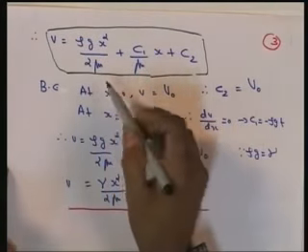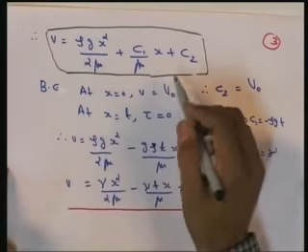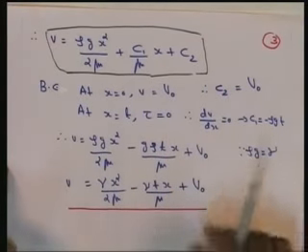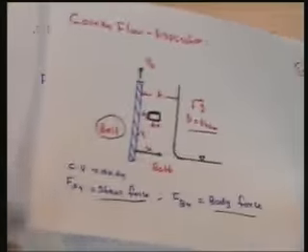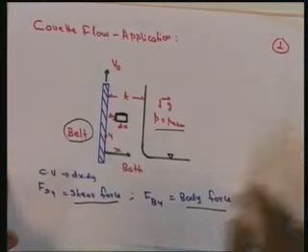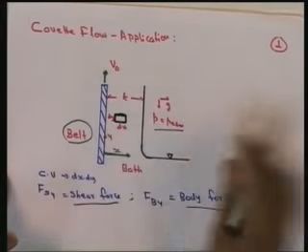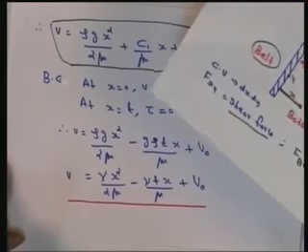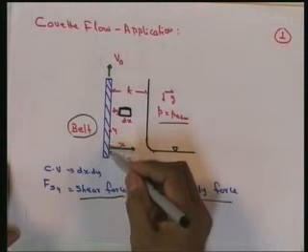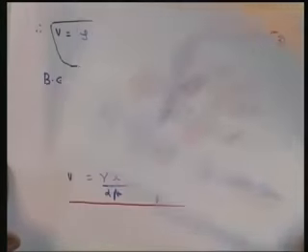So, v is equal to rho g x square by 2 mu plus c 1 by mu into x plus c 2. Here we have two boundary conditions to find out c 1 and c 2, the constants of integration. As far as the particular problem is concerned, this is one of the boundaries. At x equal to 0, that means on the face of the belt, the velocity is already known, v is equal to v 0.